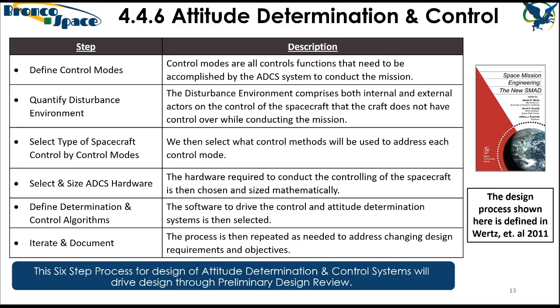On the other hand, the open air coil, it's only in the neighborhood of like 200 turns, I think. And the current's the same, but we are enclosing a much larger area. I think 50 square centimeters with the open air coils. I'm probably less than that actually. So it's a balancing act, and you have to decide not just what's going to give you the performance you require, but how is it going to fit in your system.